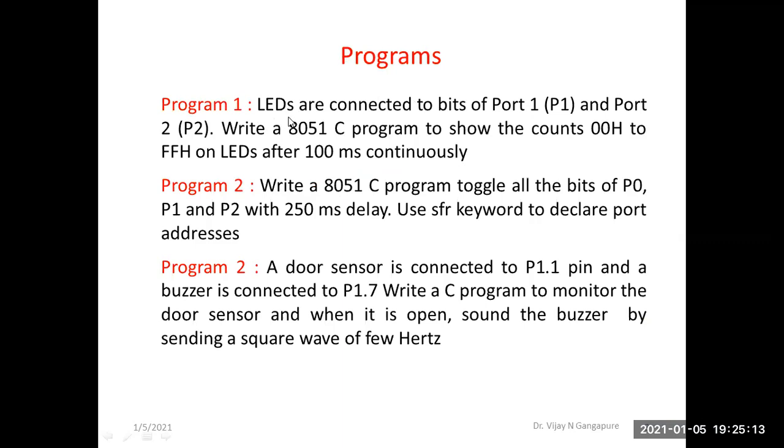The first program's statement is: LEDs are connected to bits or pins of port 1 and port 2. Write an 8051 C program to show the content 00H to FFH on LEDs after 100 milliseconds continuously.